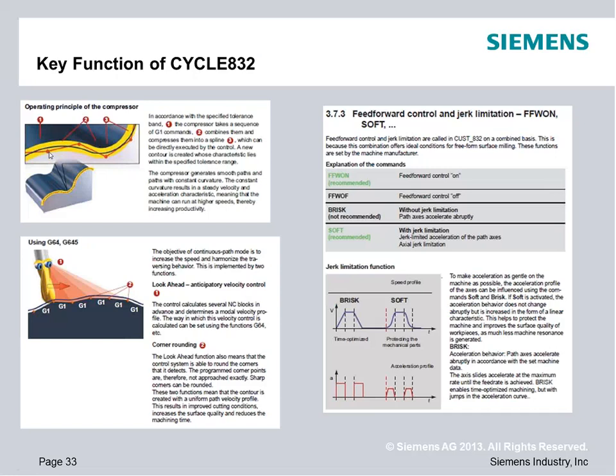If you don't know what it is, the standard rule of thumb, at least starting out: if I'm roughing, I usually put about a 5 thou chordal tolerance. If I'm semi-finishing, I typically drop that to a thou. And if I'm finishing, I usually set that to half a thou, 0.0005. That's at least the starting point, and you can play with it from there. Move it up, move it down. But if you know that discrete value, you would want to give that value.